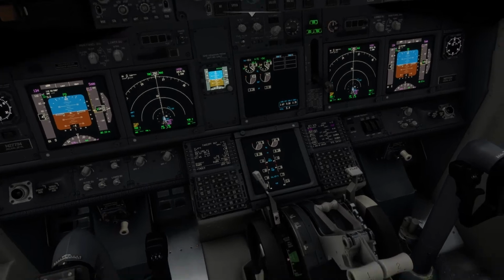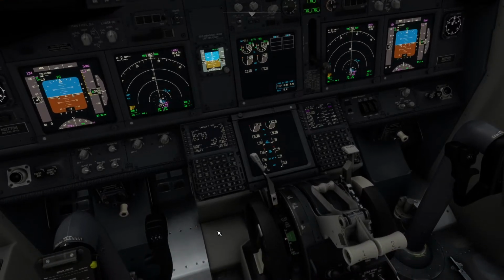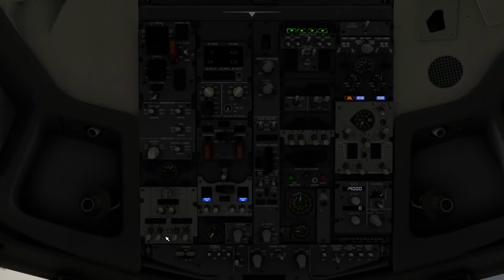That's it. And then we go with flaps 5. Flaps 5. The captain is going to perform the, how do we call it again? Flight controls check. Yeah. And the FO comes to the overhead, setting the generators to on, the engine generators to on, the air conditioning packs back to auto, isolation valve to auto, APU bleed to off, APU to off, engine start switch to continuous.